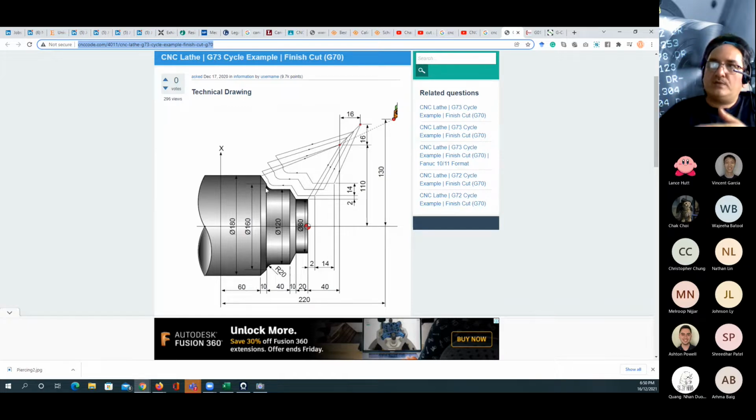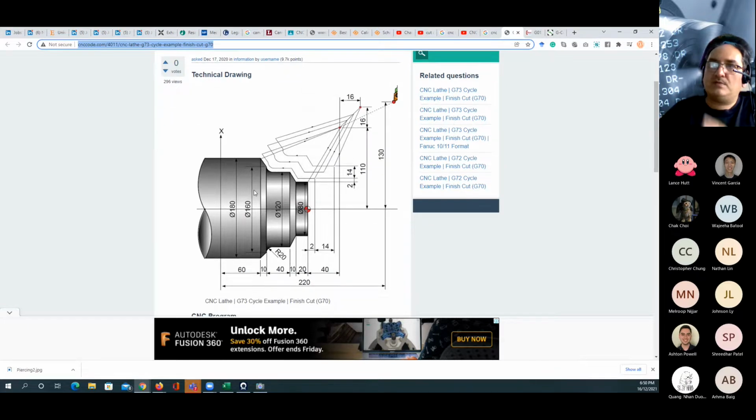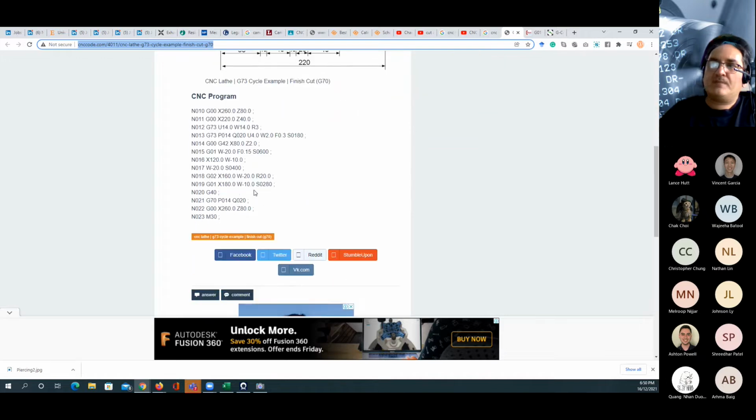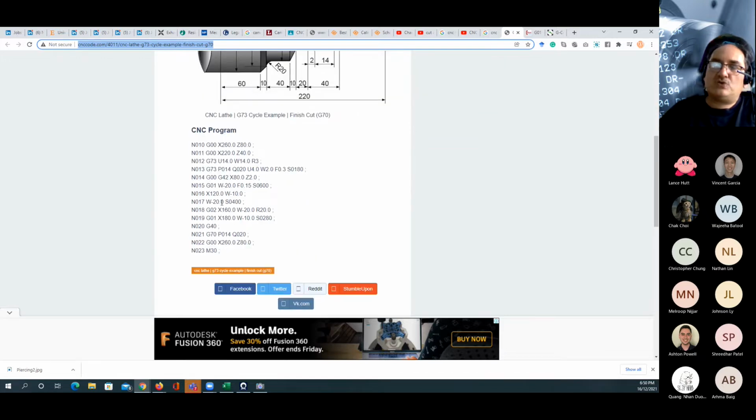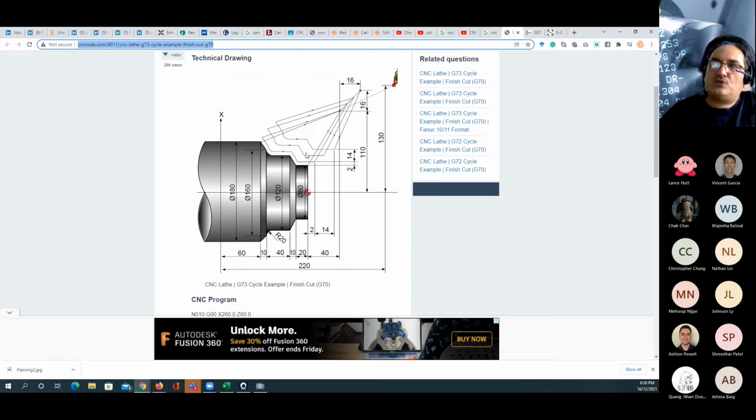I think that in the code we're going to see below, they're going to put the I and the J, but you still can put the R. It's going to be much easier to figure out. So you can see that this code is quite short because mainly, as I said, it's just making these lines that represent the arc. Your exercise is to write down the full code to peel off the part first, make it as a stepped shape, and then you are going to finish it.